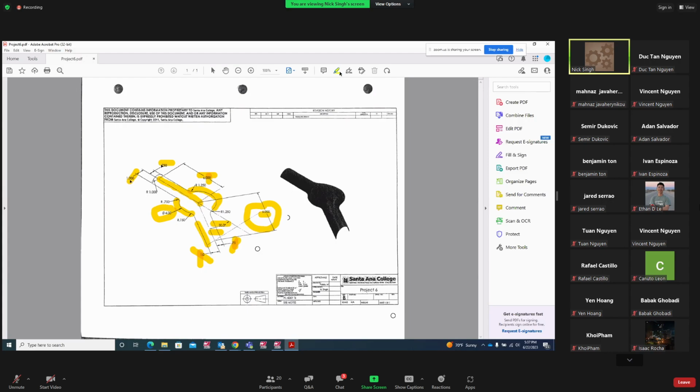And then on the right construction plane, that's where we're going to create this arc over here, 1 inch arc in construction plane right at Z. That's going to be a Z minus 6 inches right here. So this is what we're going to do.